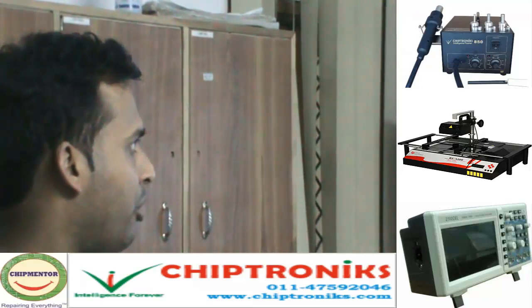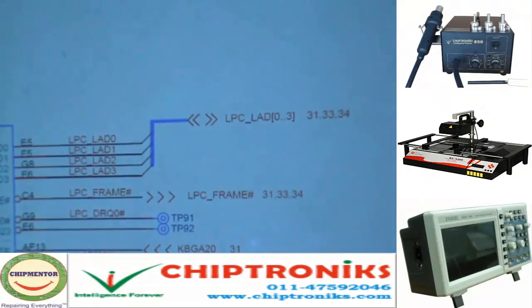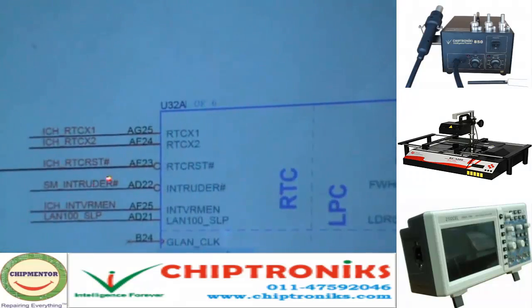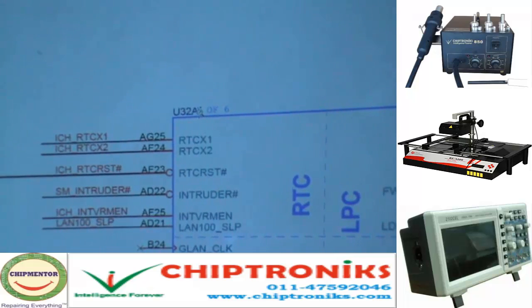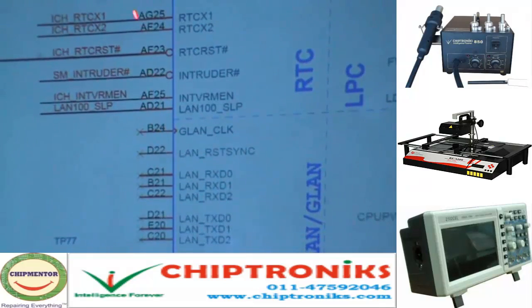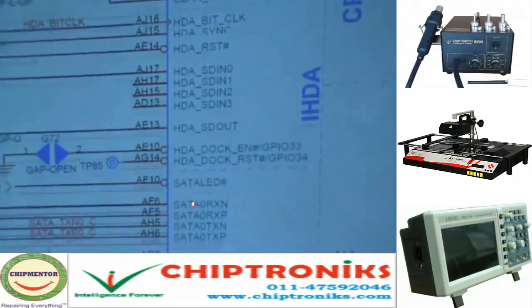So these are the two important signals. We'll go back, we'll quickly go to page number 19. This is the RTC, the real-time clock, the first starting point of any testing. This is fed through a crystal. Your ICH requires one crystal, your IO requires one crystal, because they start before the clock generator.